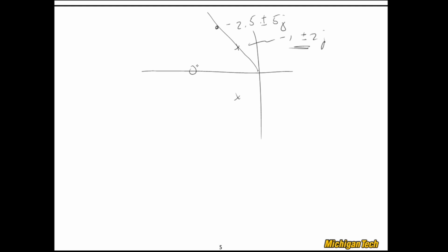Now what happens with the lead compensator is I plug a 0 and a pole in there, and what I'm going to do is use these two quantities to add phase to the loop transfer function so that my root locus will go through this point. It'll actually bend this root locus from going up like so, it'll bend it around like this. So the question is, how much phase do I need? I better go to another page that I have some clean paper to work with.